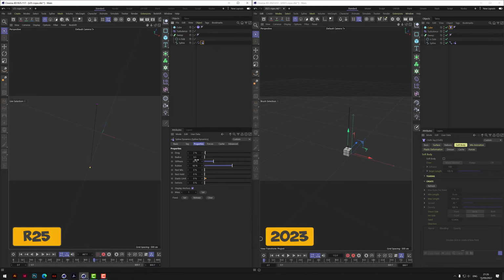Don't think there's any settings we can make here. I mean, we could take the stiffness up, and we could take the rubber off so there's no rubberness on this rope cable. The radius, we can actually match the radius here of the end side, so we could put that in at 1, and we need to do that on the new one as well, but let's just stick with this for the minute. Forces, yeah, it's including the turbulence because we've not added it in there as an include, so it will add it automatically.